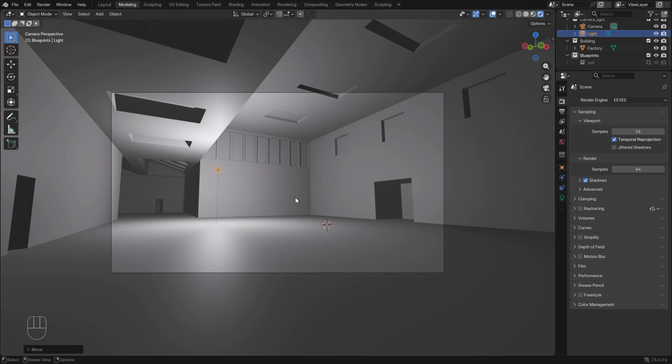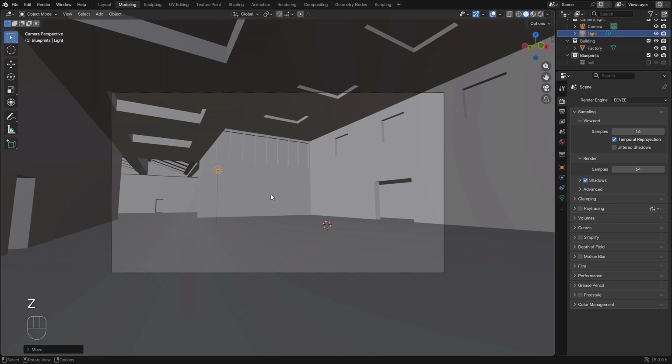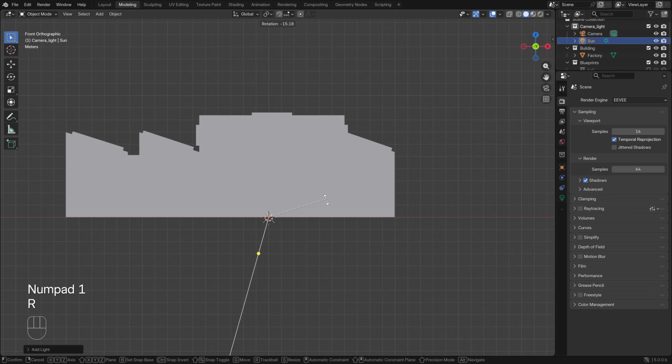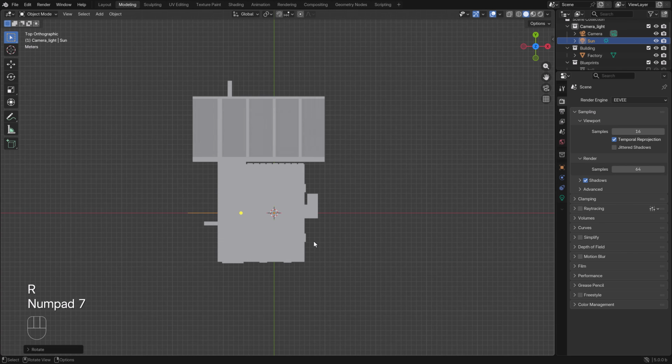And by adding the first set of materials, it will start looking much better. We do some lighting. We replace the lamp with a sunlight and pick a sky, a generated procedural sky. Later on, we will use an HDRI. All right, enough information. We delete the lamp. We go to camera light, add, and we go to light and sunlight. And I like to rotate it slightly. Again, this is just preview lighting to have an idea how it looks. We won't use it after we added the windows, otherwise it looks simply dark.